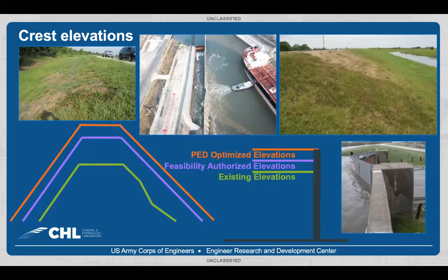This was a combination of more accurate wave and water level modeling and response and statistical modeling across the board. An adaptability elevation was analyzed for resilience. The adaptability elevation for feasibility was 2 feet over the authorized elevation. The adaptability for optimized corresponds to the elevation that just met the limit state for SLC2. This adaptability elevation was used for the final design of critical features such as pump stations and gates. The pictures are of existing floodwalls and levees in the study region that have been exposed to the forcing hazards.